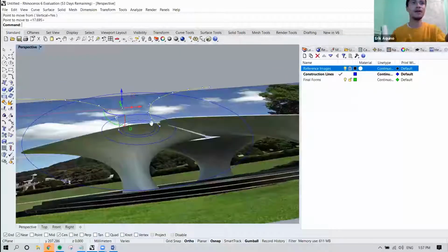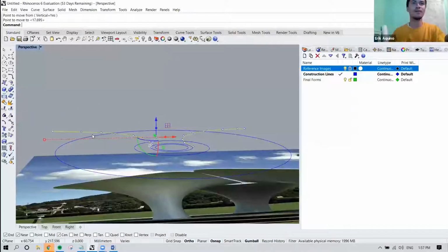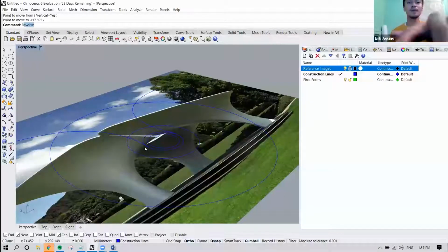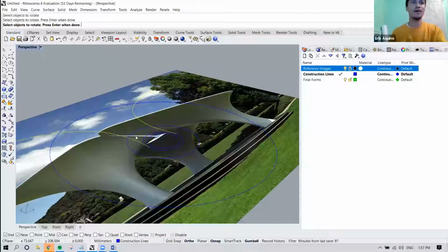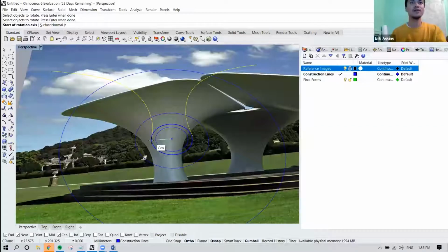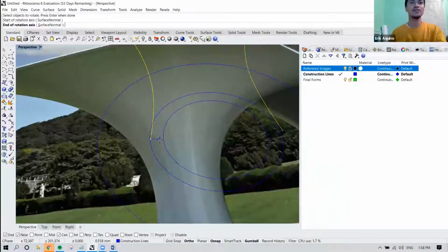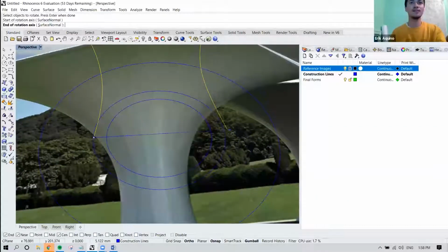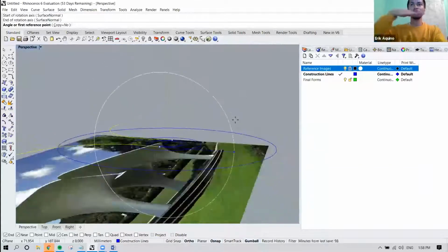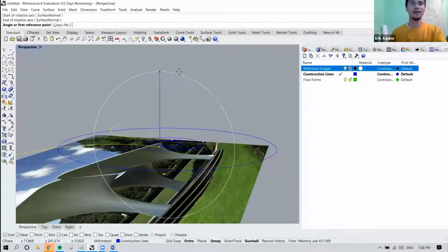And what we'll do now is rotate 3D. So if you recall from yesterday's tutorial, we did a rotate 3D command, which I could select my objects and then create our 3D axis. So I'll just select the endpoints for one side of the axis, the second endpoint for the other side, and we're literally just lifting it up so it'll be a 90-degree angle that we're creating.